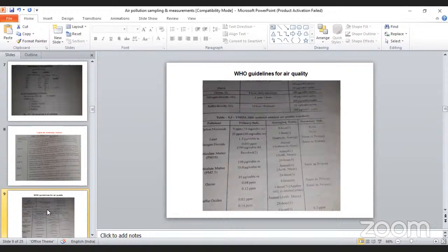Now we'll discuss how we do the sampling. I told you there are different methods. An absorber must be used. They can use any solid, liquid or gaseous medium for absorbing the gaseous sample. And one more, filters are also being used. And stack sampler and Impinger bottles, cross-section of sampling, the Impinger bottle, these are all very common things people have adopted for doing the sampling.